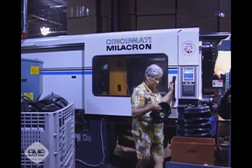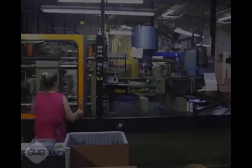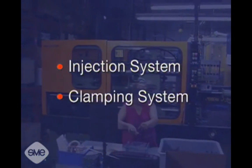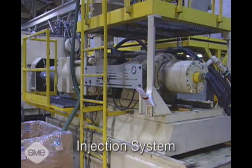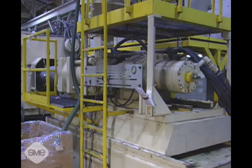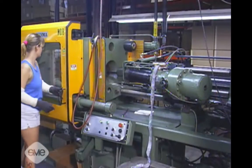Injection molding machines range in size and complexity from desk-size units up to machines the size of a small house. All injection molding machines are a combination of two systems, an injection system and a clamping system. The injection system heats the thermoplastic material to its appropriate viscosity or flowability and then forcefully injects it into the mold. There are two types of injection mechanisms: the reciprocating screw, which is the most common, and the two-stage screw.